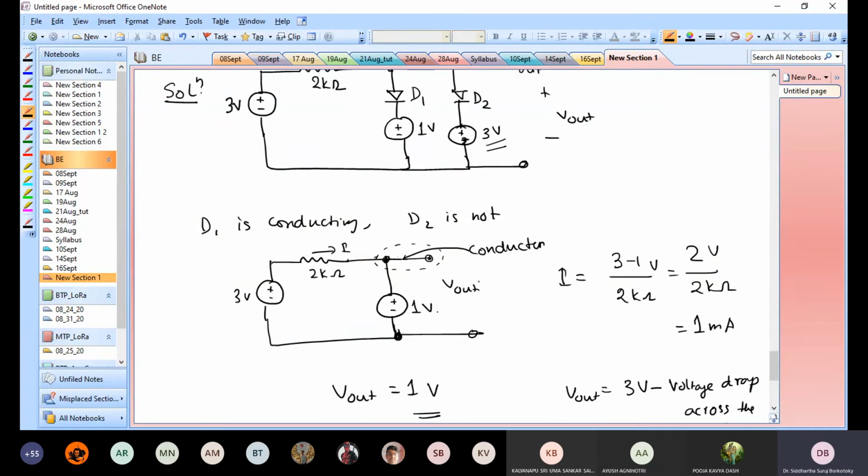If the voltage is something different, the circuit behavior changes. So in your analysis, in order to do some sort of a loop analysis or mesh analysis, you have to make the judgment: is the diode open circuited or short circuited? Because if I do a mesh analysis assuming an open circuited diode, it's something different. If I assume a closed circuited diode, then it's again something different.